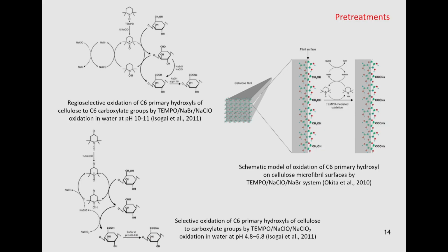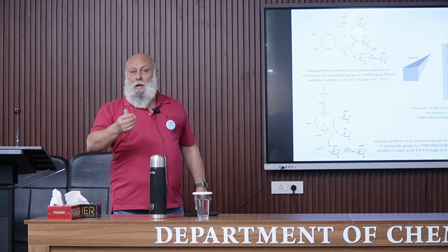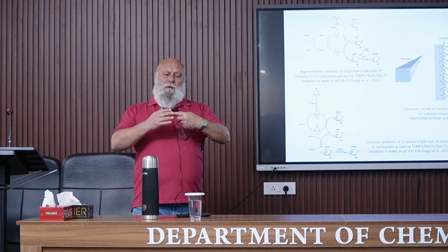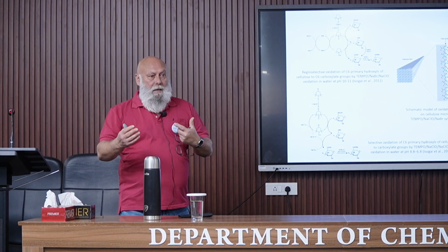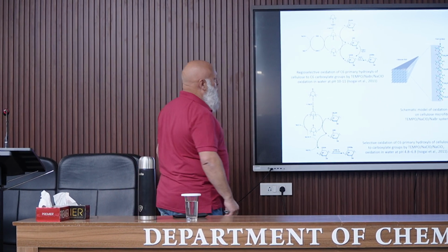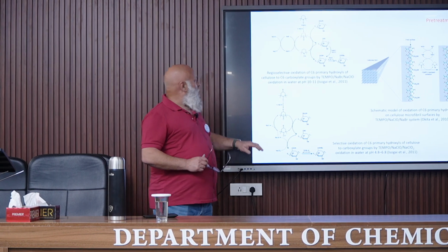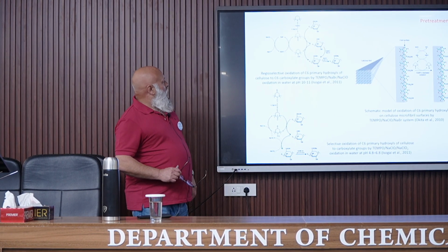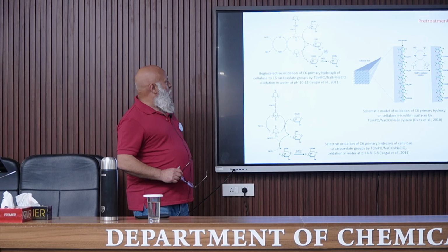Regarding the chemical treatment, different treatments have been proposed, and all of them aim to introduce some charge at the surface of the molecules in order to have repulsion and to facilitate the separation of the nanofibrils. The most well-known is the TEMPO oxidation treatment, which is briefly reported here.